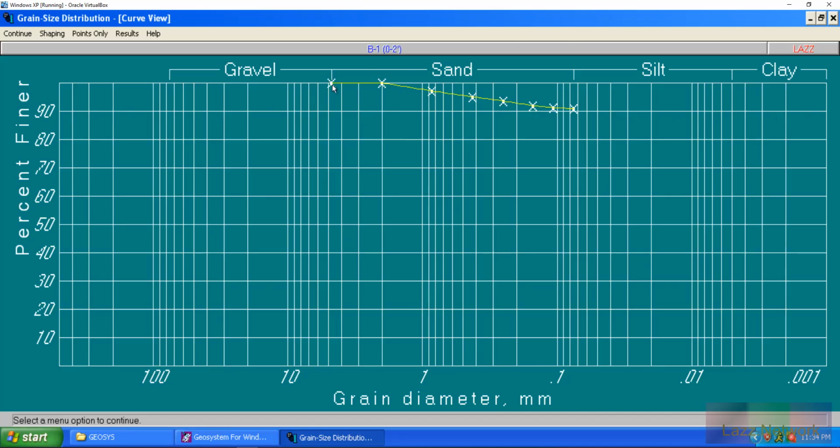So from our number 4 sieve all the way down to our number 200 sieve, this is considered our sand portion here. And I hate to jump around, but technically usually gravel ends around 3.5 inches. So that's where that point is roughly. It's either 3.5, some people do 6 inches. It's an adjustable setting that you can do, but typically somewhere around there is where gravel ends. I hate to jump around like that. So then you have your silts and clays right here.